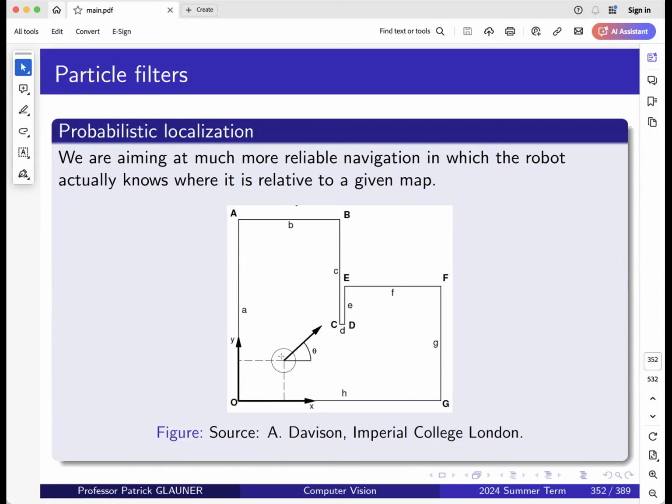Now, as the robot keeps moving around in this map, it will obviously have uncertainty in its motion. So if we first want to move the robot to the right and up and then back and up here and down, the robot will internally keep its state, so it's X, Y, and theta. But at some point, this is just off from reality, because if you want the robot to move over here, it will maybe move somewhere around there, then up and rotate. So where the robot is in the real world will more and more diverge from where the robot thinks it is, just because the robot thinks it really moved 10 meters, but maybe only moved 9.8 meters. It didn't fully rotate as wished.